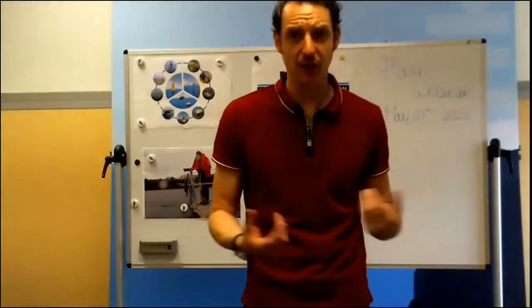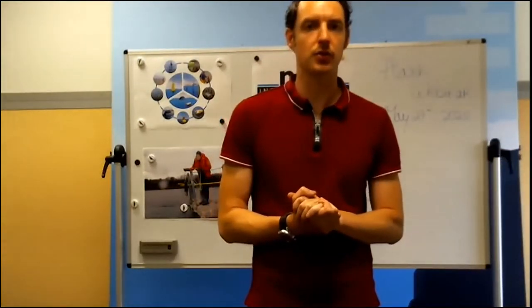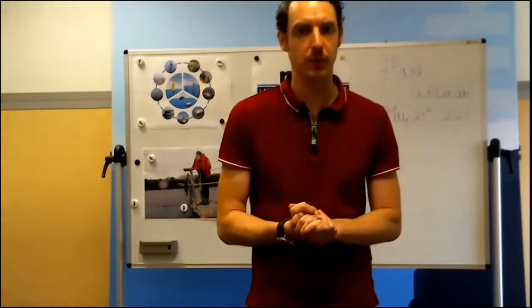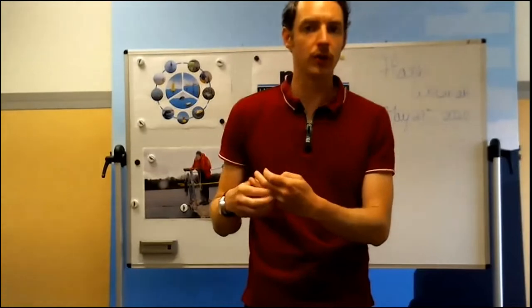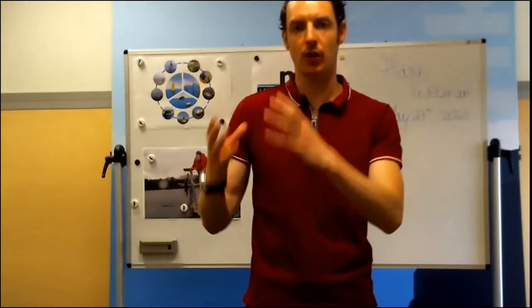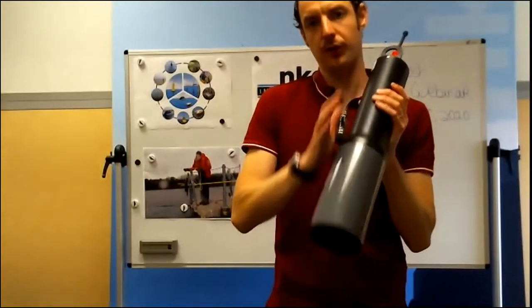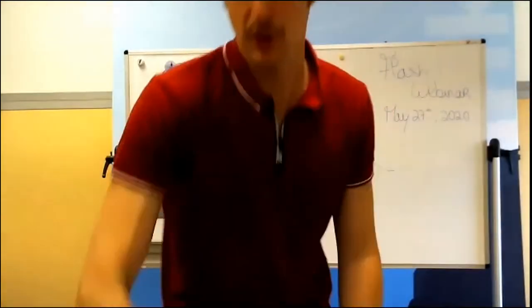Also, what period of the year? Typically, if we are in Europe and in winter, you do not need to go very often to clean the probe. Whereas if you are in summer, maybe a month or 2 months, not only to clean the sensor, but also to clean the external part of the sonde might be necessary. But generally, the sensor remains clean.